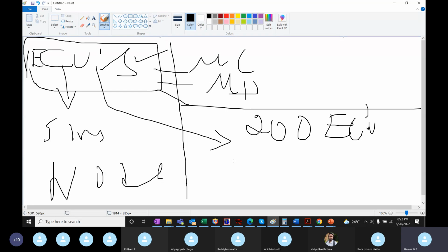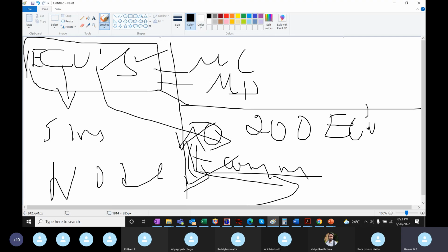So now the ECUs have to communicate. There should be a radar and cameras to detect objects around the car, and the camera and radar provide the input to an ECU, and that ECU provides the input to the brake ECU, where the brake ECU applies the brake. This is the communication happening here. It could be a sensor, radar or camera, any one input detecting the object, and it provides the data to the ECU, where the ECU decides whether to apply the brake, brake completely at 100%, or slow down the car. This communication happens using a communication protocol, which we are already aware of.